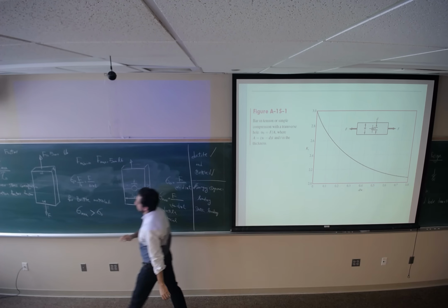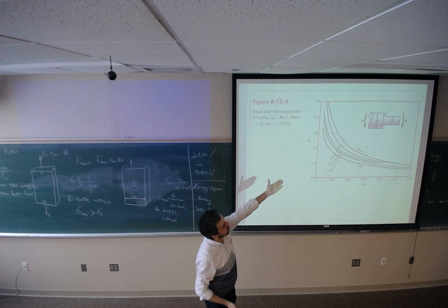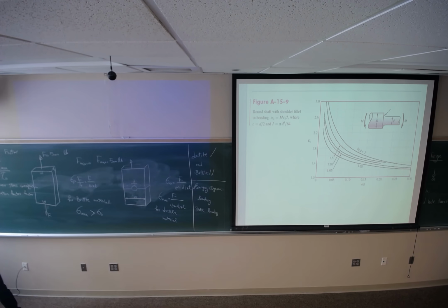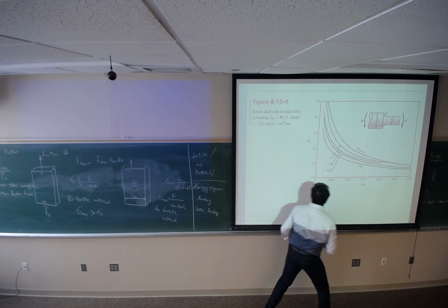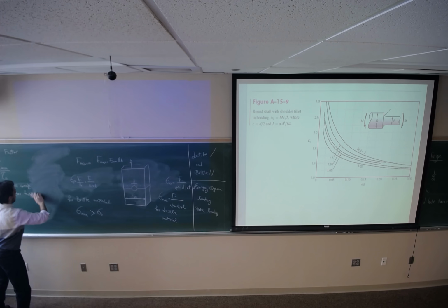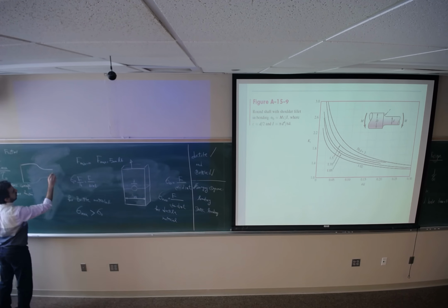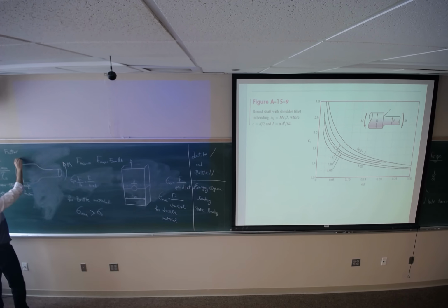So this is how the concentration factor is found. If I have a shaft with different diameters and the shaft is under bending moment, the diameter of the bigger part is capital D, the lower side is lowercase d.